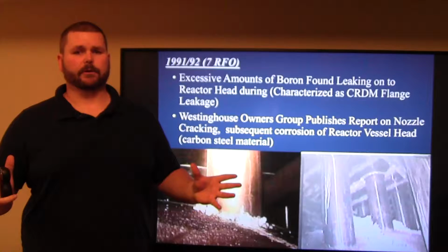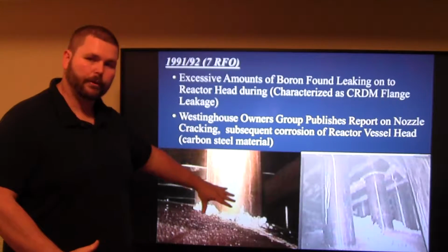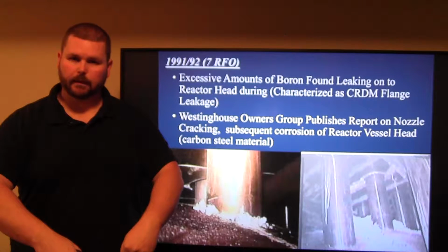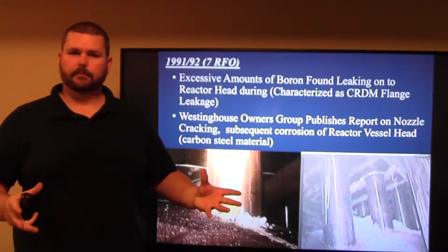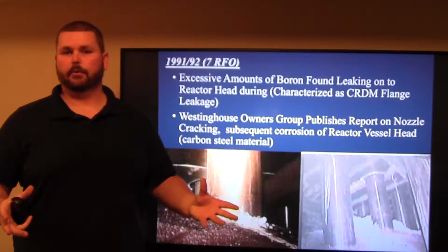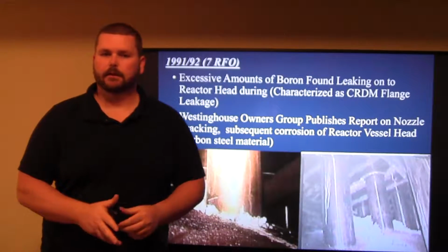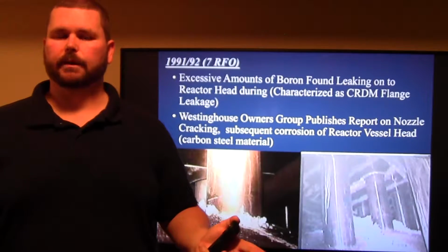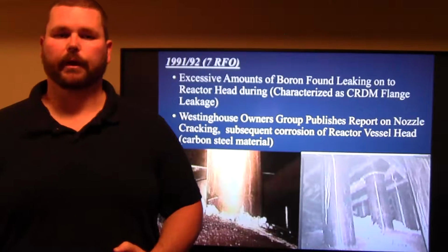They're like, whoa, there's a lot of boron on the head. They did an inspection, they found this popcorn, they called it. It was basically the boric acid came down from the flange, leaked on there, fizzled, and made popcorn-looking stuff out of the boric acid. And the heat of the head was at 550 degrees, which just caused it to boil away. So they thought it was okay because there was no mechanism of corrosion. They took the moisture away.